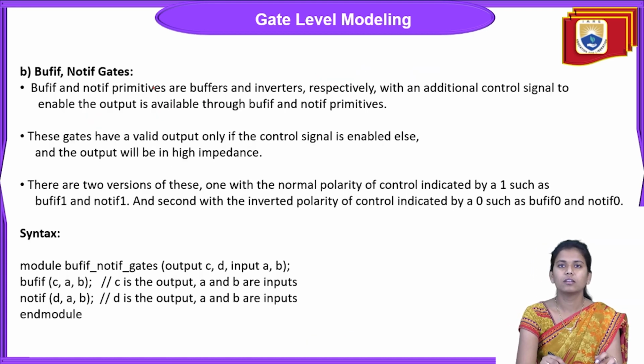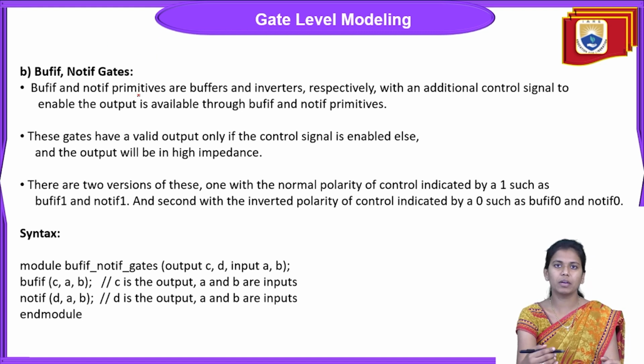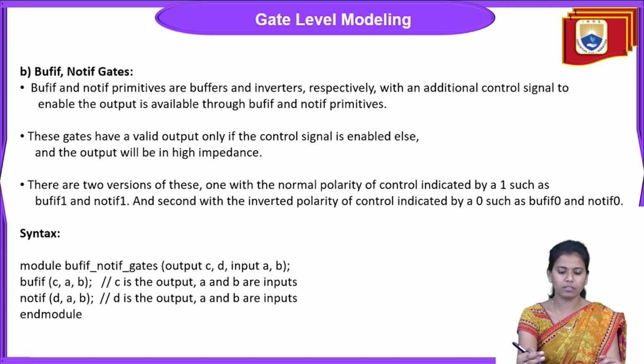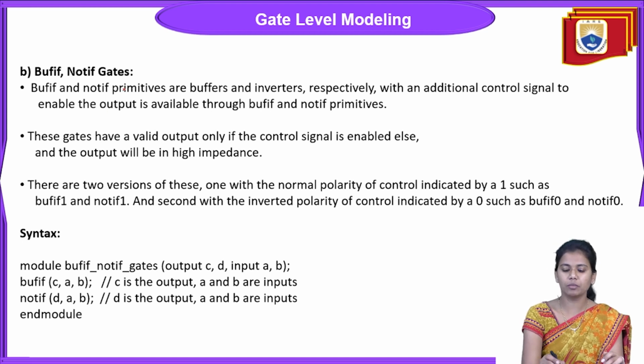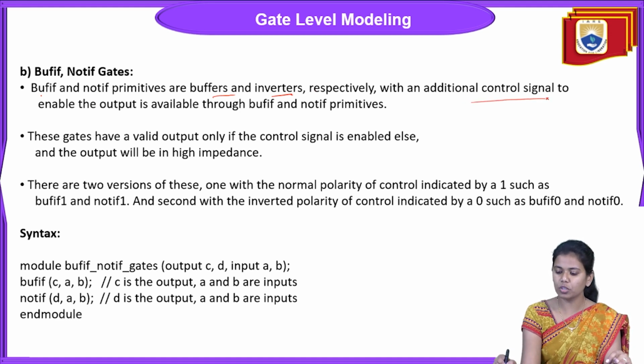Coming to the second example, BuffIf and NotIf gates. How can we write the syntax by using BuffIf and NotIf gates? BuffIf and NotIf are primitive gates, meant for buffers and inverters respectively. BuffIf is a buffer and NotIf is an inverter, with an additional control signal to enable the output.